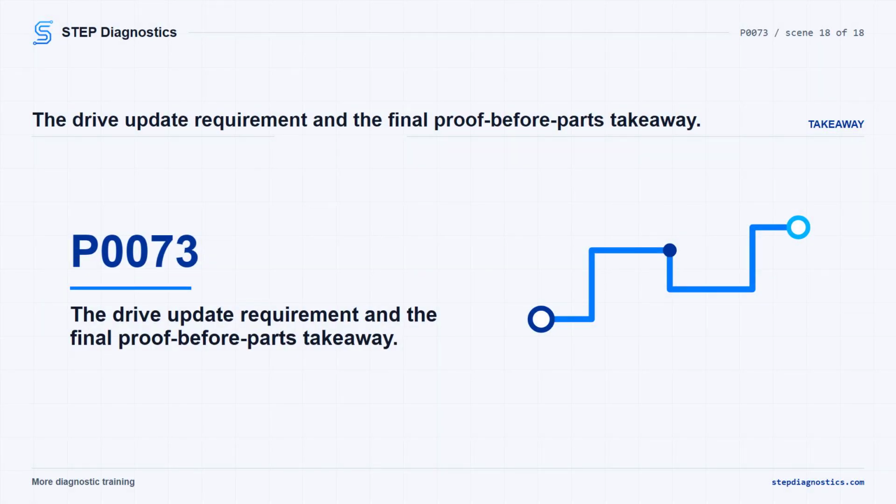For the performance monitor, the check can depend on the vehicle sitting after an 8-hour cold soak, with the compared temperature values above -64 degrees C, -83 degrees F. A rationality fault is typically looking for the ambient temperature signal to be not within 10 degrees C, 15 degrees C, 18 degrees F, 27 degrees F of the other engine temperature sensors.